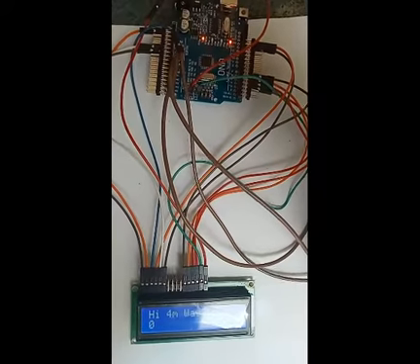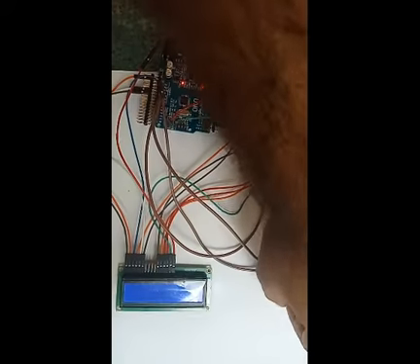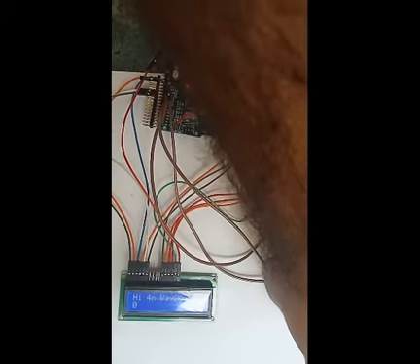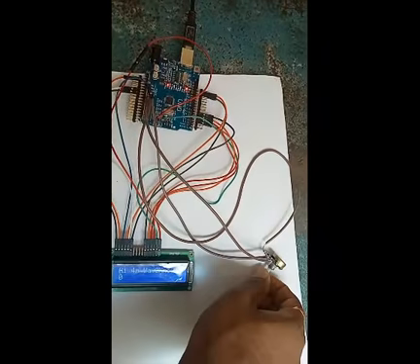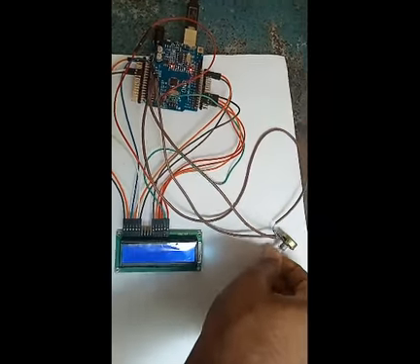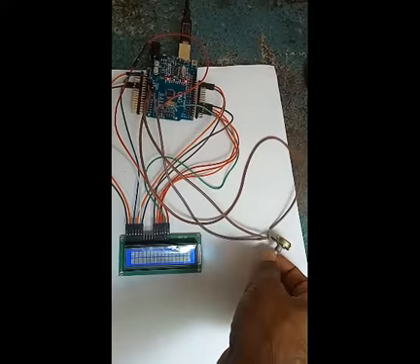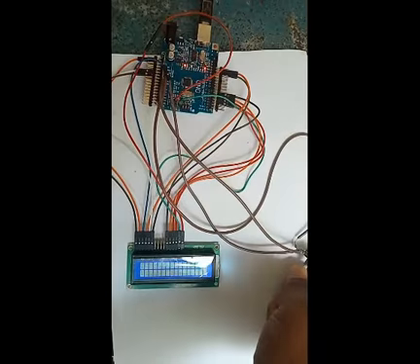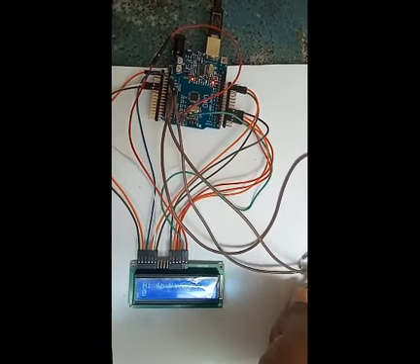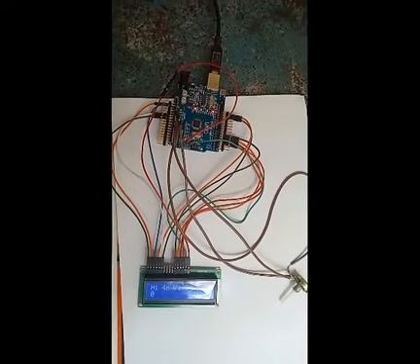For example, you can see here, if we adjust this, it goes off. Okay, and then again we are trying to adjust. See, with a minimal setting, with a basic setting of this pot, you can see live here, it goes off. And sometimes you can see these blocks in the LCD. That is because the problem could be related to the contrast pin voltage. So this is one tricky thing for the beginners.